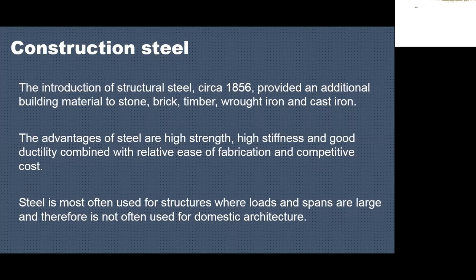Steel is most often used for structures where loads and spans are large, and therefore is not often used for domestic architecture. For example, in house construction or 2-3 story building construction, steel is not used often because it has a high load carrying capacity.